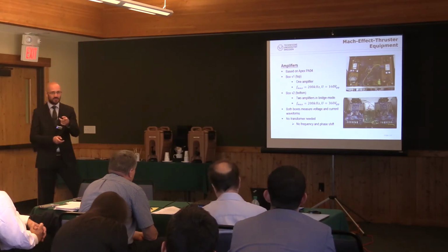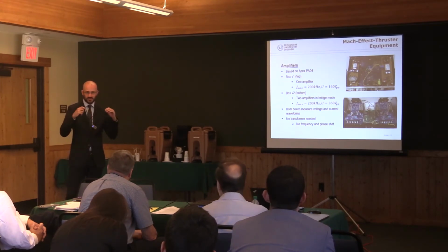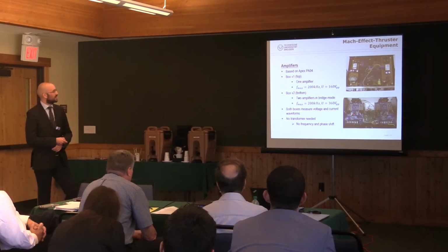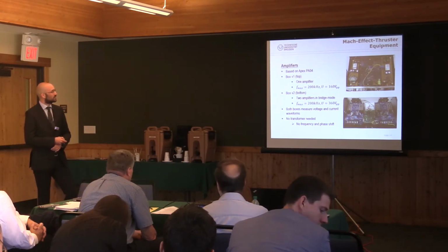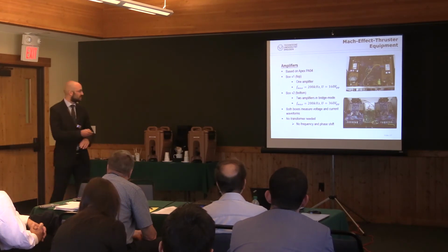I think that's very similar to what David Jenkins does with his. Your D-class amplifier also is in bridge mode, right? So you have double the voltage. And we can go up to 360 volt peak there, and that's basically the picture. In this box there's a preamplifier and some filters to smoothen the signal.